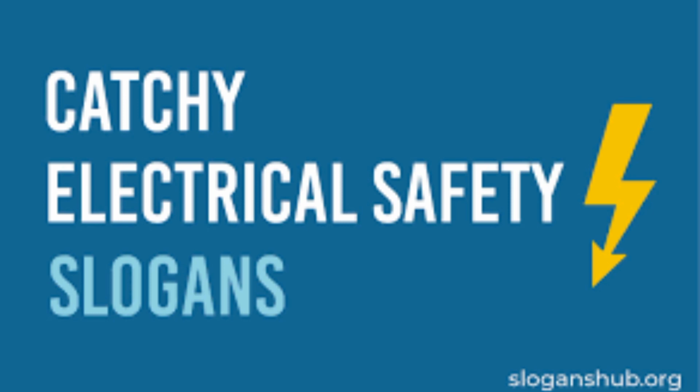If you are working near overhead power lines of 50 kilovolts or less, you or any equipment you are using must not come any closer than 10 feet from the lines. And always follow good practices for electrical activities.